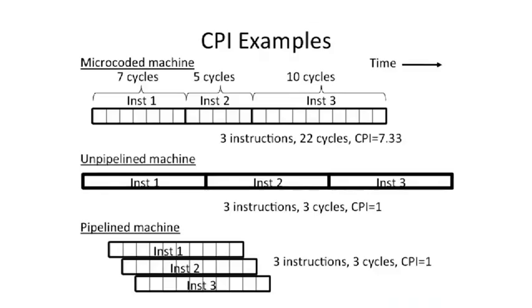And in an ideal pipeline machine, we'll actually have multiple instructions executing at the same time. So time goes left to right on this graph. And we'll be able to cut the instructions. And in an ideal world, we'll have a CPI of 1. And our clock period will also be short. And you can see this is sort of smaller than those other solutions. And this is why we start to think about pipelining. But we're using transistors to do this.